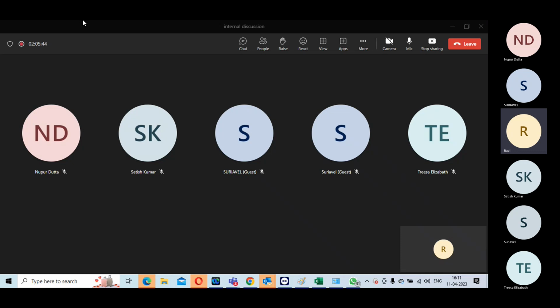This is the source. Here is what you have to hand place, those cells, before you do your placement also. Or if you have done your placement by any mistake, you have to move the cell accordingly to make sure things are working. Hand place the mux, hand place if possible the clock gater, but otherwise it is okay. Okay, because you are seeing that because of clock gating.